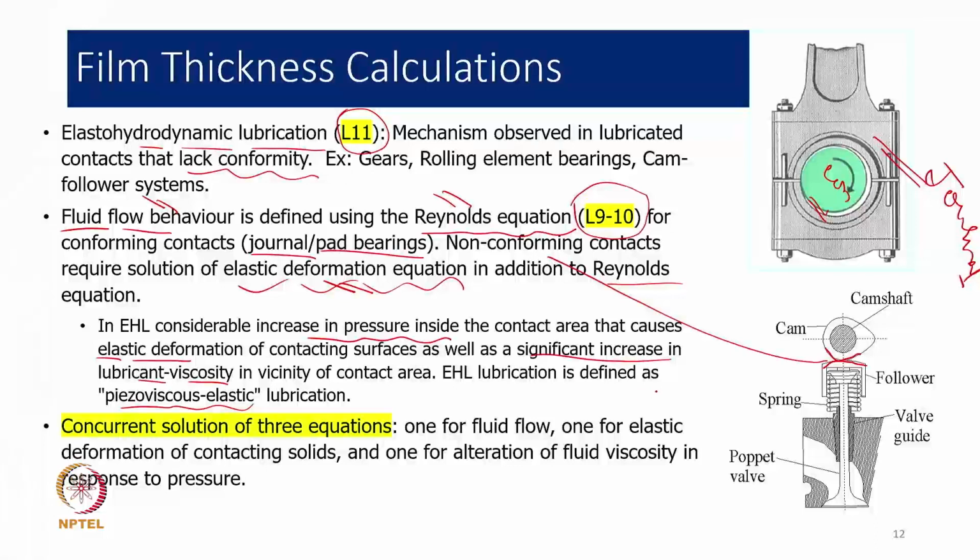So that's why EHL is very important, and that's why many times EHL lubrication is also defined as a piezo-viscous elastic lubrication mechanism. So what is the major challenge? We require a simultaneous solution of three equations: fluid flow, the Reynolds equation, the elastic equation, and, in this situation, the alteration in the fluid viscosity equation.